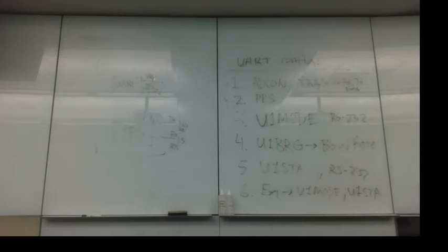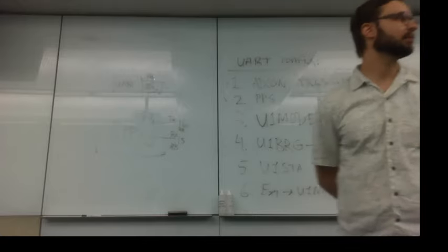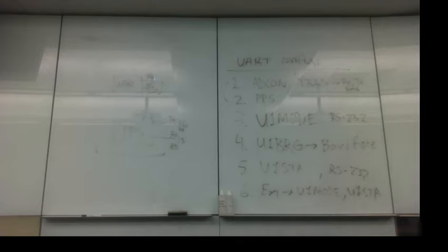What sorts of terminal programs are people using these days? Does anyone know what's on the lab computers? Has anyone used a terminal program to do serial before? Yeah, PuTTY, that's the one I've always used. It's free. I think 9600 is standard for PuTTY RS-232.